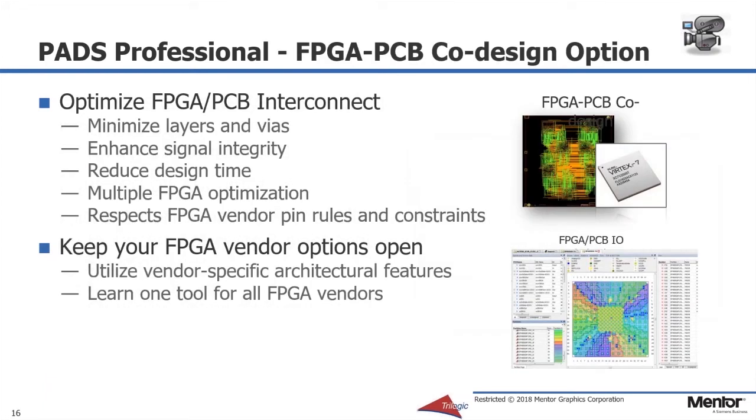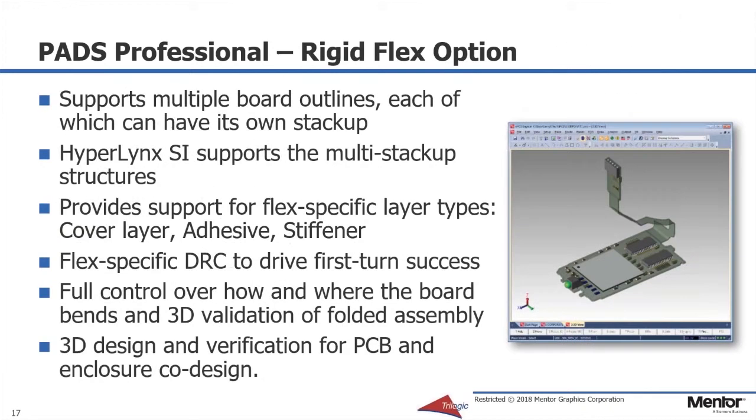One of the advanced options available with the PADS Professional is FPGA-PCB co-design. This software automates the optimization of the FPGA and PCB integration. It understands the architectural features of your specific FPGA and facilitates forward and backward changes to the FPGA and the PCB pin designations to improve the routability of the design.